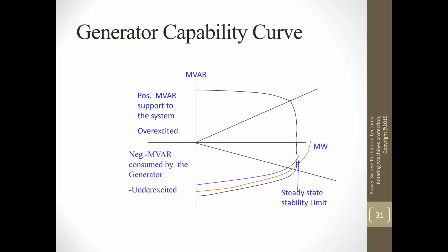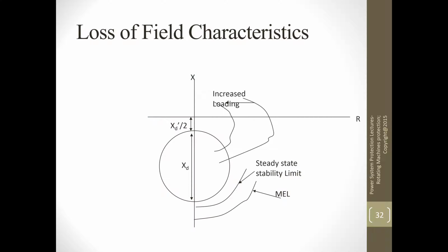This is a big thing in the North American Electric Reliability Corporation, PRC-025, and there are other PRCs, reliability standards for compliance and protective relay standards, which provide very detailed analysis on how to set this and what to do. So again, as I mentioned, C37.102 provides a very good explanation of all the protective functions, whereas NERC provides a lot of details on how to set it, what to check for, and how you can prevent misoperation for a fault which is not inside the generator.